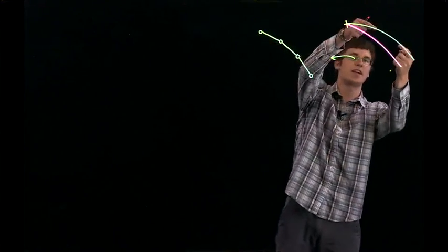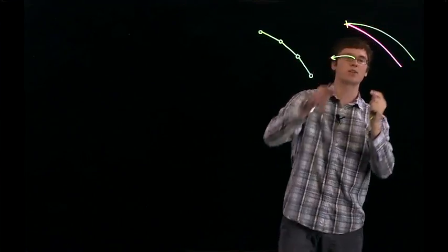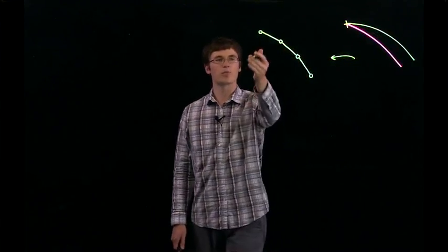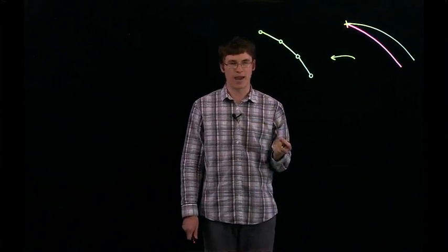Now, this model is good for two reasons. First of all, it's physically motivated. Experiments have shown that the rat whisker is very stiff in the axial direction, or in this direction, but is much less stiff in the transverse direction right here. Second of all, it gives us a place to start with computationally. By choosing the number of links in the whisker, we can both control the amount of accuracy that we have, and we can also control how much computation is needed to compute a solution.